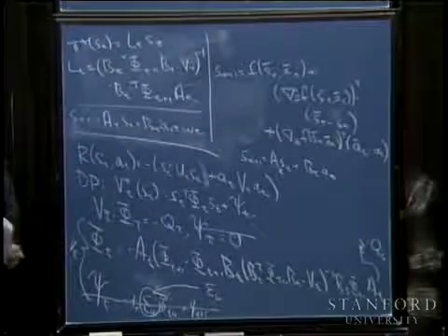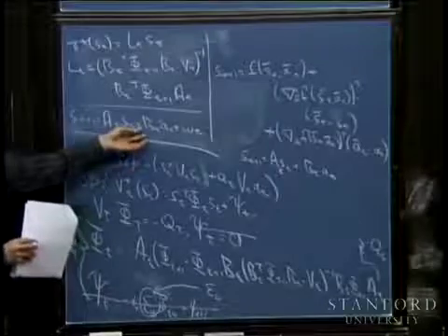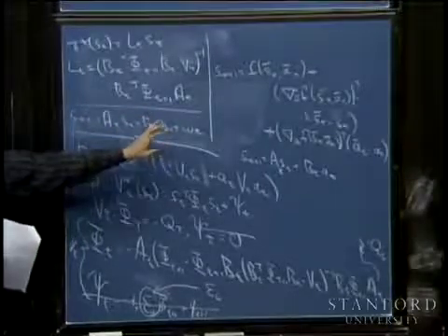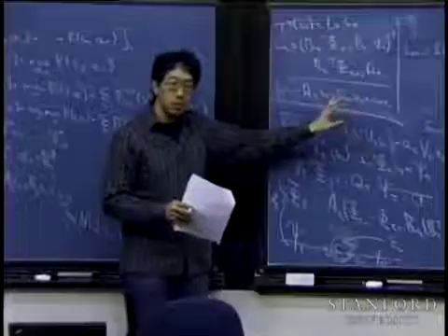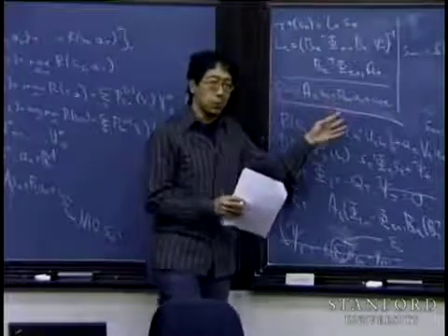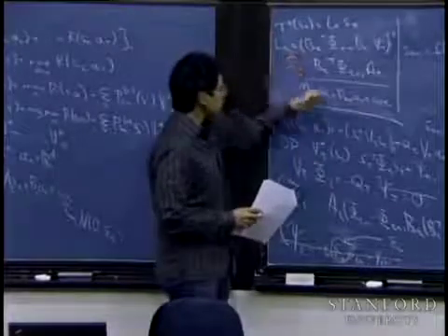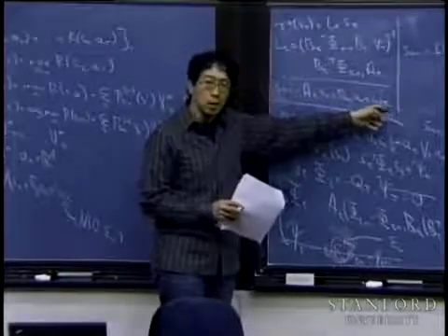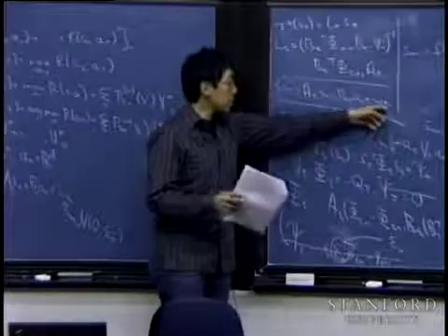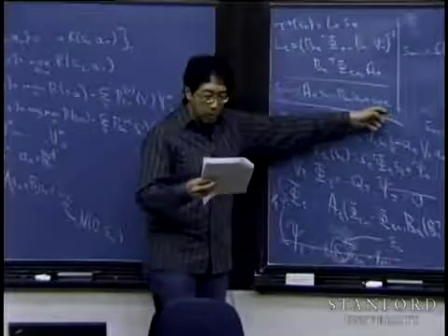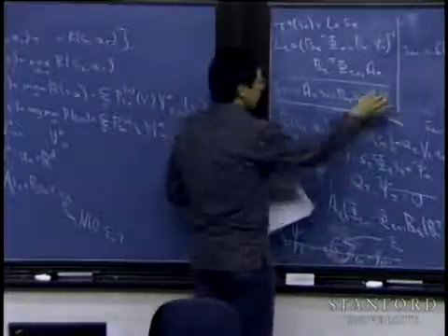So this is a very special property of LQR systems. And once you change almost any aspect of this, if you go away from a linear dynamical system, or if you go to discrete states or discrete actions or whatever, this property will no longer hold true. But this is a very special property of LQR systems, that the optimal policy does not actually depend on the noise magnitude of these noise terms. Okay? The only important property is that the noise term should have zero mean. And so there's this intuition that to compute the optimal policy, you can just ignore the noise terms.